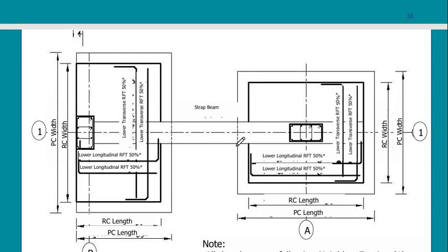I take the maximum of the two cantilevers to design the bottom. I take the middle to design the upper reinforcement. So this is for the beam. For the two foundations, this is my new location of my imaginary load, and this is the same location of my imaginary load. The load here is different from the original, and the load here is also different from the original.